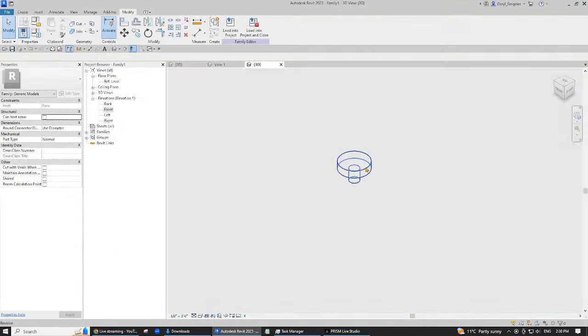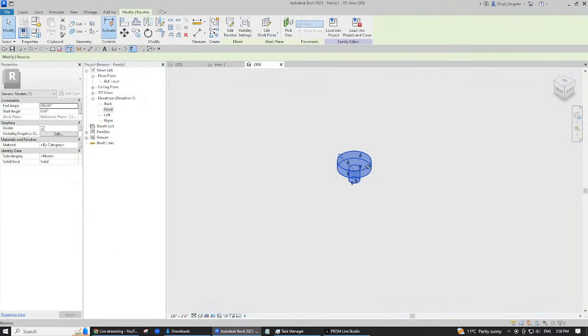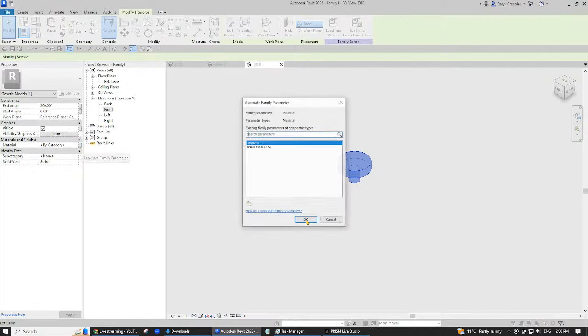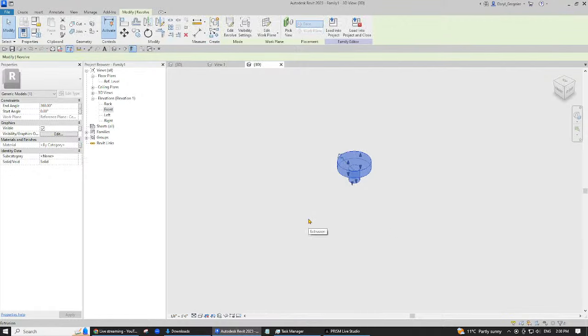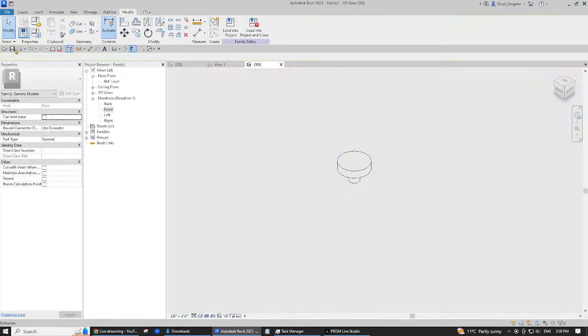Now what I have to do is just pick on this element and make its material be the parameter here, the little button, knob material. So it's unassigned but linked to a parameter. So the material of the revolve is set to be the parameter knob material, and it's undefined. Click out, okay, and save.